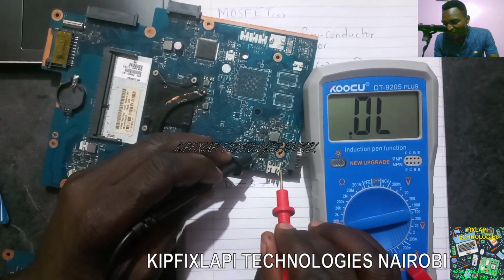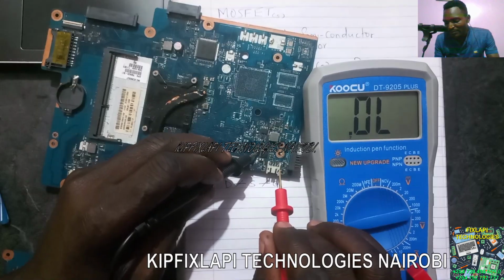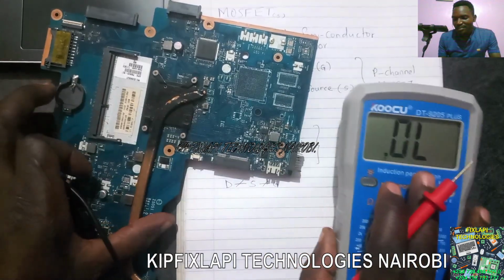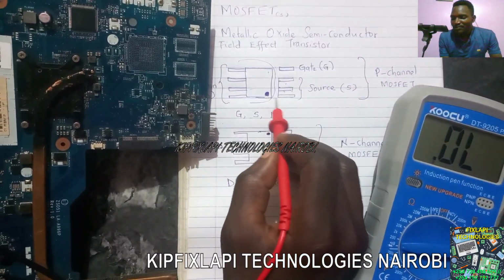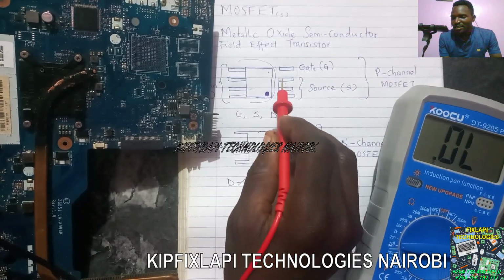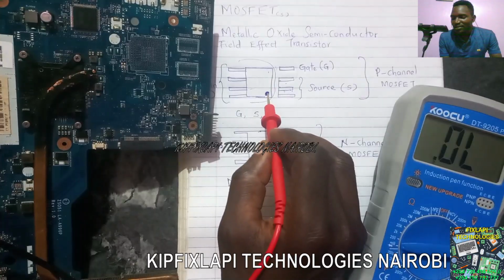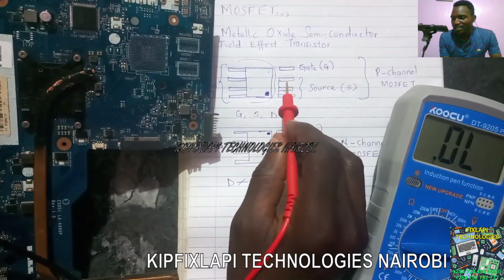You can see I have a dot here, so pin number 1, 2, 3 from that particular area where there's a dot, all of those are connected together. So I can place my probe at either of these three.